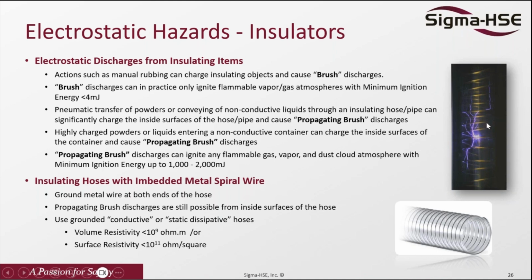However, you still have propagating brush discharge, where you can see in the picture at the top right there's a breakdown voltage between the metal and the insulator, which is the plastic. So anytime you're using this kind of flexible hose, you need to ensure that the hoses are static dissipative or conductive hoses and the wires need to be bonded at each end.